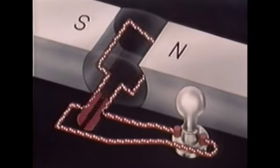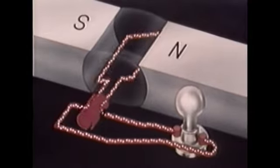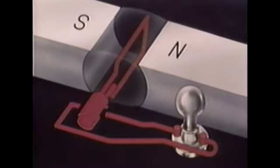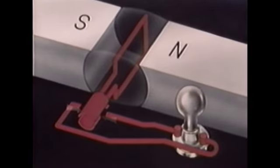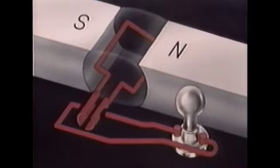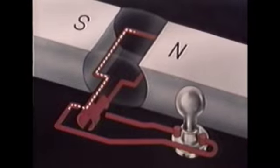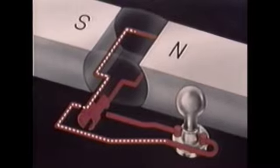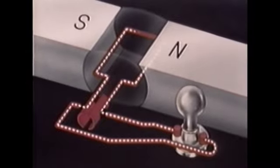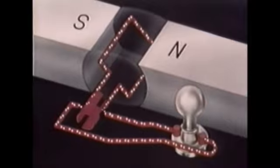If the contact would continue, as it did in the AC generator, the current in the circuit would reverse its direction. But the brush, which connects the commutator to the external circuit, breaks contact with the first commutator segment and makes contact with the second. The induced current in the rotating coil is now opposite in direction from that of the previous half cycle. But since the commutator has switched the coil connections to the opposite sides of the circuit, the induced current from the second half cycle again passes through the external circuit in the same direction.